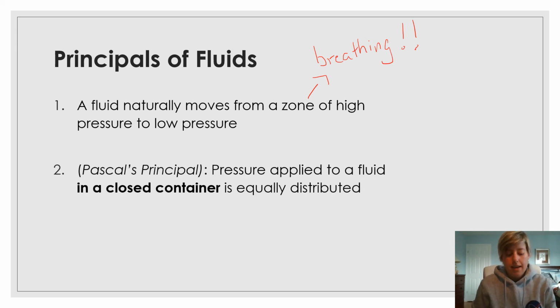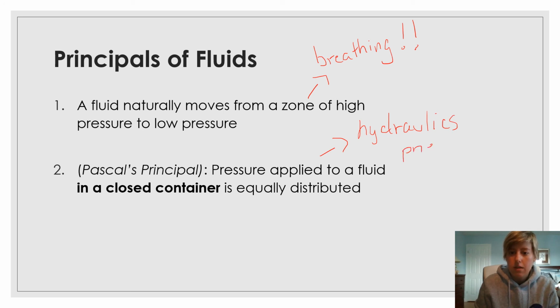Our second, and this is called Pascal's principle, is that the pressure applied to a fluid in a closed container is equally distributed. And when we're saying closed container, that means the container does not let anything escape. And this is actually used a lot in hydraulics and pneumatics. If my container is closed, when I'm applying pressure, the fluid is easily distributed, so I can actually manipulate how my different components move.